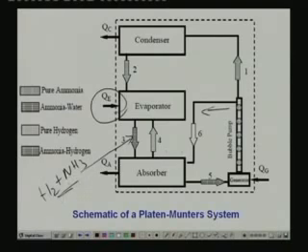Okay. So, when they come in contact, what happens is ammonia is taken out from this mixture. That means this solution absorbs ammonia and it cannot absorb hydrogen. So, hydrogen is left out and ammonia is absorbed. And in this process hydrogen temperature increases. Since its temperature increases, it becomes lighter and it moves up to the evaporator. So, that is how the hydrogen circulation is maintained. So, you have a closed hydrogen circulation from evaporator to the absorber because of the buoyancy effects.